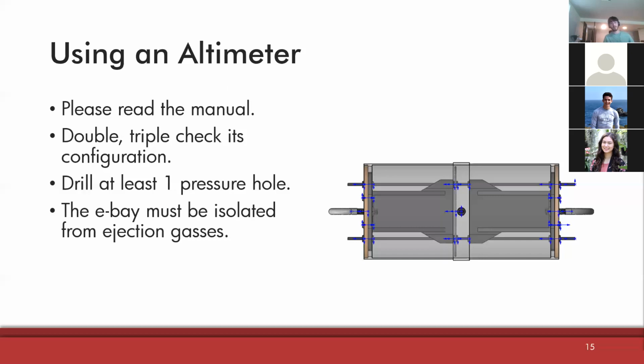And so in a worst case scenario, that can lead to your rocket thinking that it's actually like 500 feet off the ground and it needs to deploy another set of parachutes. That's not necessarily a catastrophic error, deploying extra parachutes, but as I mentioned before, that could lead to a lot more drift than you had planned on, possibly leading you to power lines and highways and other such stuff.